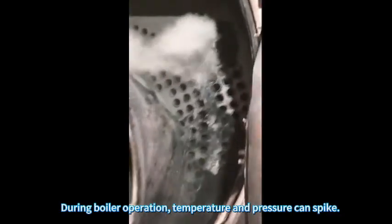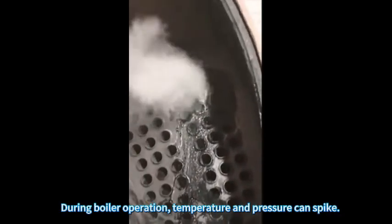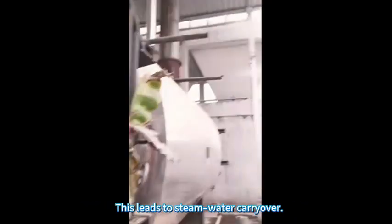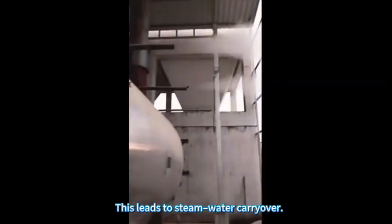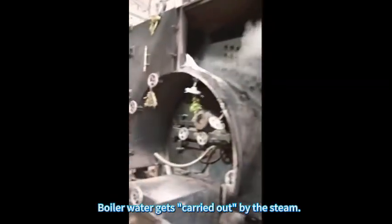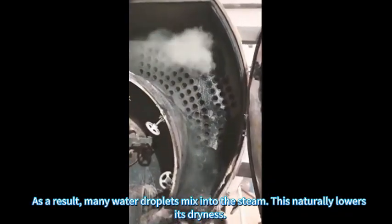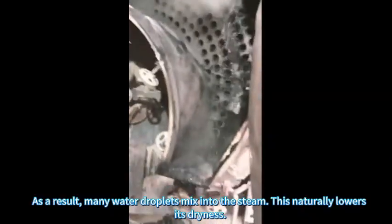During boiler operation, temperature and pressure can spike. Pressure and load might also change greatly. This can cause the drum water level to shift wildly. This leads to steam water carryover. Boiler water gets carried out by the steam. As a result, many water droplets mix into the steam. This naturally lowers its dryness.